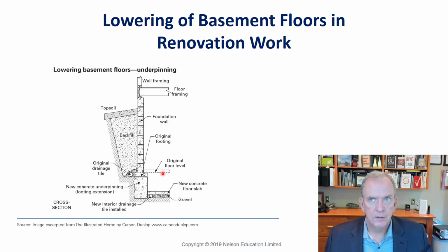Usually it's like a 7 to 10 ratio. So if you go down 7 inches, you've got to come out with the bench 10 inches. If you go down 14 inches, you have to come out with the bench 20 inches. And the reason for that is the forces coming down on the wall don't come perfectly straight down. They actually come outward. And if you just excavated this straight out or under the whole foundation and you left this underneath, then the house would collapse. So if you're going to put a bench, you have to leave this angled out, and then you have to put a concrete, literally bench or box here, and that prevents the wall from settling and pushing out.